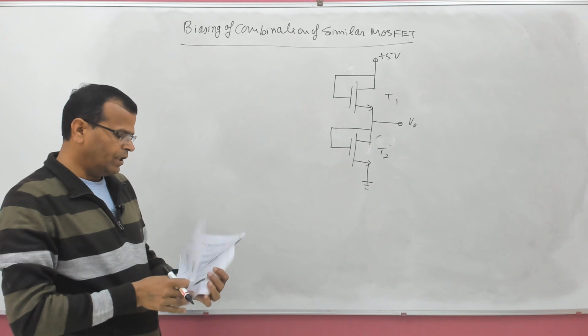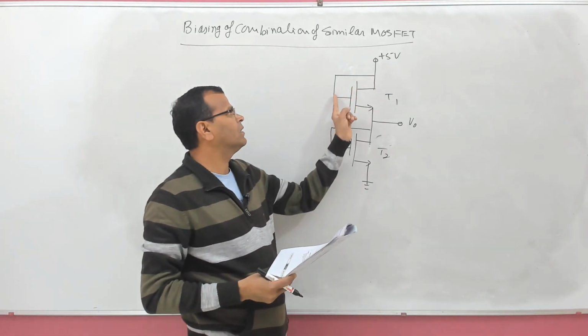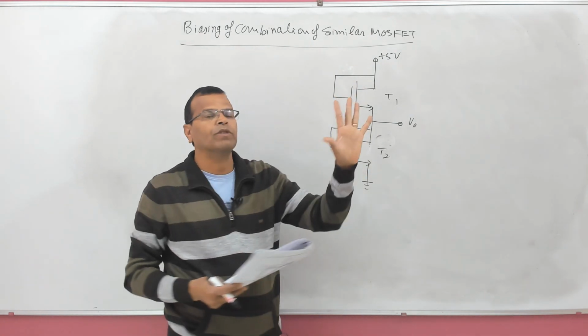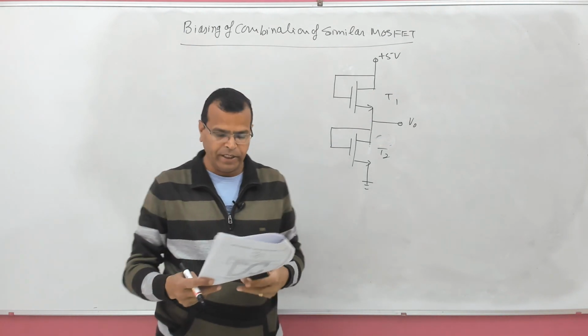So, the question here is, remember one thing, whenever drain is shorted with the gate terminal, that MOSFET always operates in saturation region, that is fixed, right?